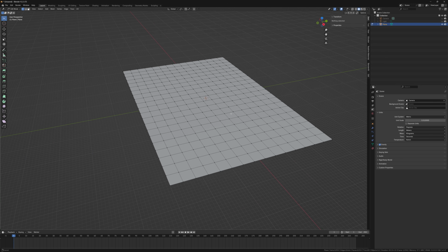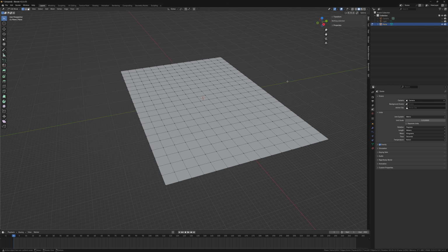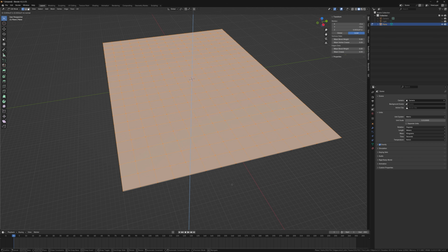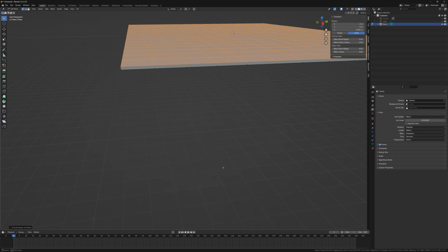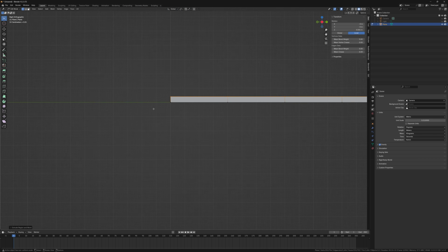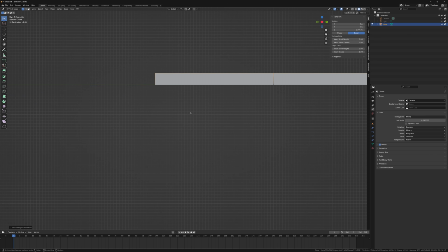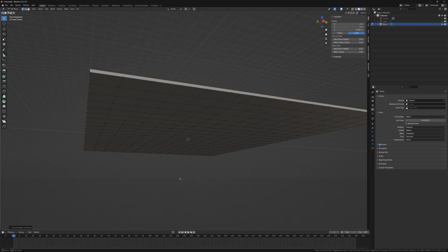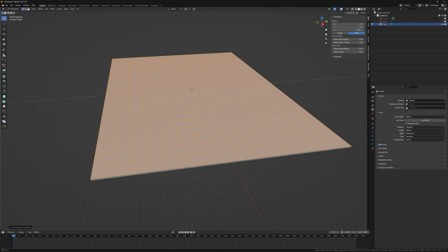Now, this is our main grid. So first of all, I'm going to hit A to select all, E to go upward, and then it's about 0.004, should be about 4 millimeters. We snap to this axis, we can check it using Alt and the scroll wheel to snap to a certain view. So you can see this is now 4 millimeters up. So that's a basic thickness we have now. So you have a separated bottom layer from the grid.